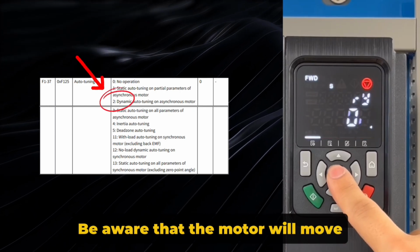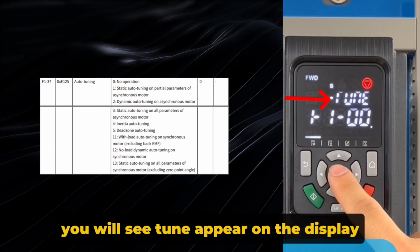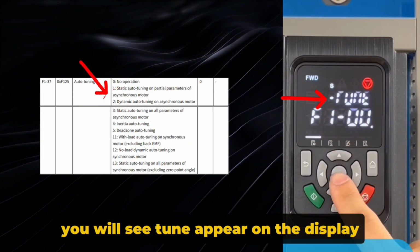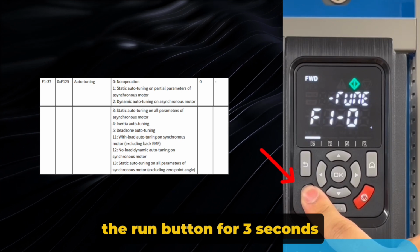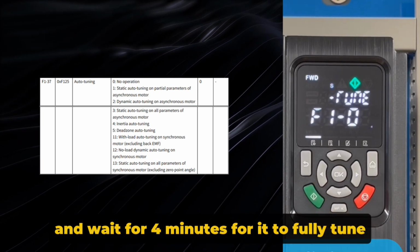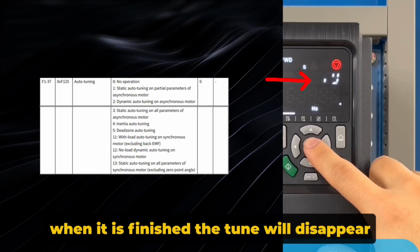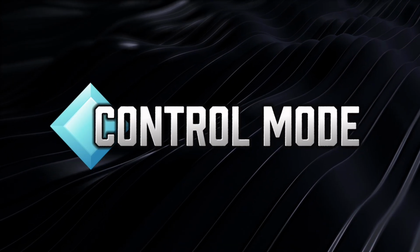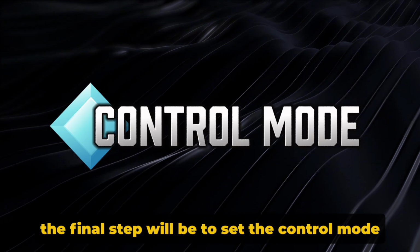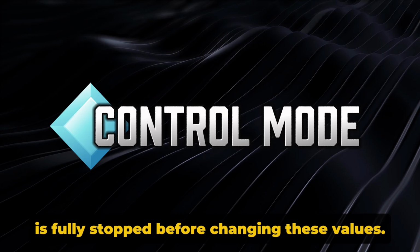Be aware that the motor will move if you select dynamic tuning. Once you press OK, you will see Tune appear on the display, at which point you press and hold the run button for 3 seconds and wait for 4 minutes for it to fully tune. When it is finished, the tune will disappear. Now that we have finished configuring the motor parameters, the final step will be to set the control mode. Please ensure that the motor is fully stopped before changing these values.